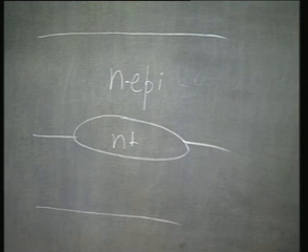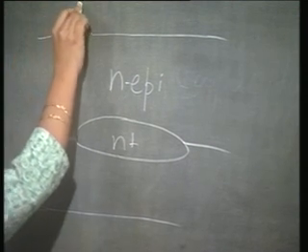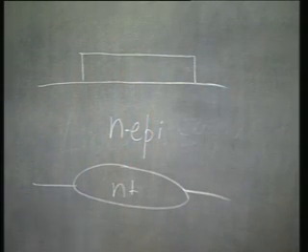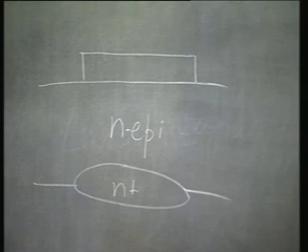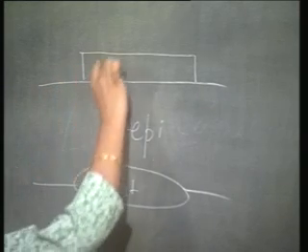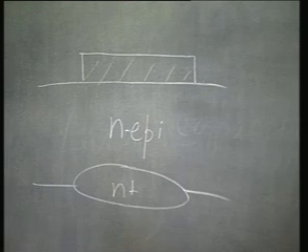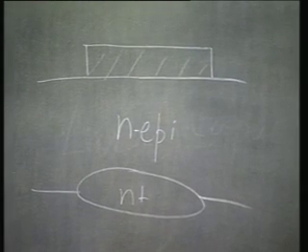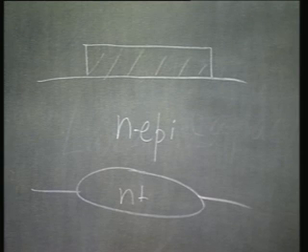Let us assume that the substrate was 1 0 0, the epi layer is also grown in the 1 0 0 orientation. Okay. Now, let me protect my active region like this, okay, using oxide or photoresist or whatever. By a suitable protection, let me protect my active region, and now let us subject it to an anisotropic etch. So, what will happen?